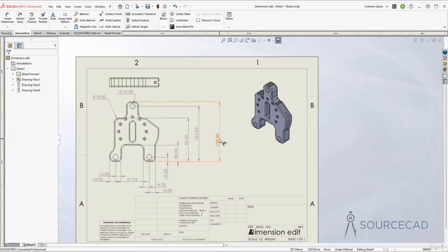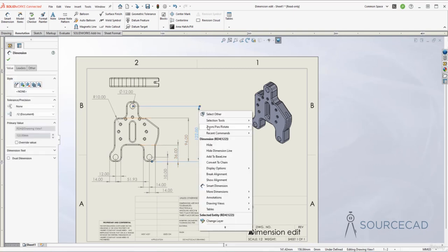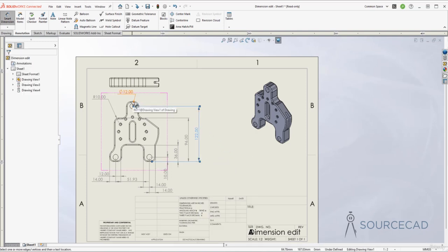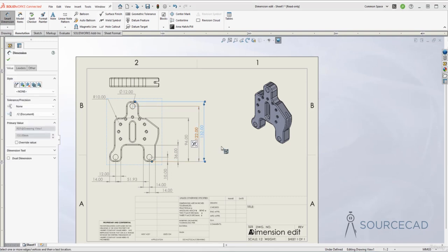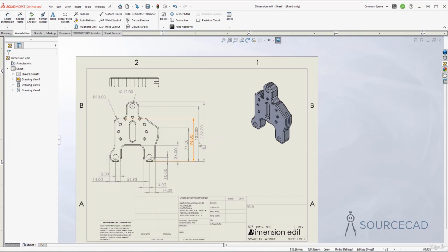Now, if you want to align it again, you can just select it, delete it, and now select any existing dimension which is already linked with the set, right click and select add to baseline. And now specify the point where you want to just link this dimension, and here it is, it's added again. Now, not only that, you can also specify new points. For example, let's say we want to just add a new dimension maybe here. So that's added. Now, since we have added new dimensions here, the spacing is now changed, and as you can see, it is not uniform.